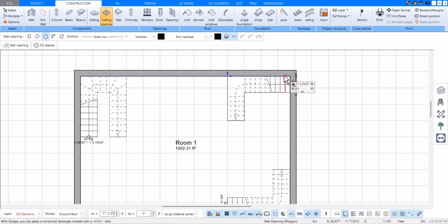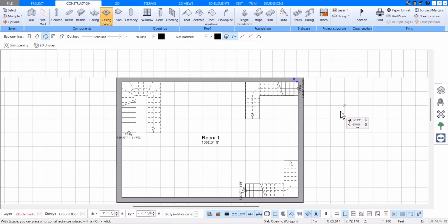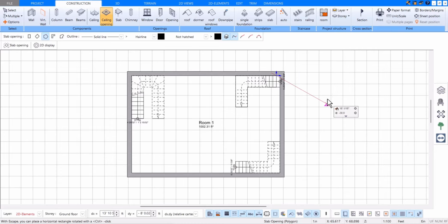Once we later add an additional upper floor, the staircase can be neatly guided upwards through the ceiling opening, and it will also be correctly displayed and visible within the 3D mode. With these detailed steps, you can easily draw a staircase in Plan7Architect, fine-tune its appearance in 3D mode, and if necessary, adjust any ceiling cutouts or openings accordingly to fit your design.